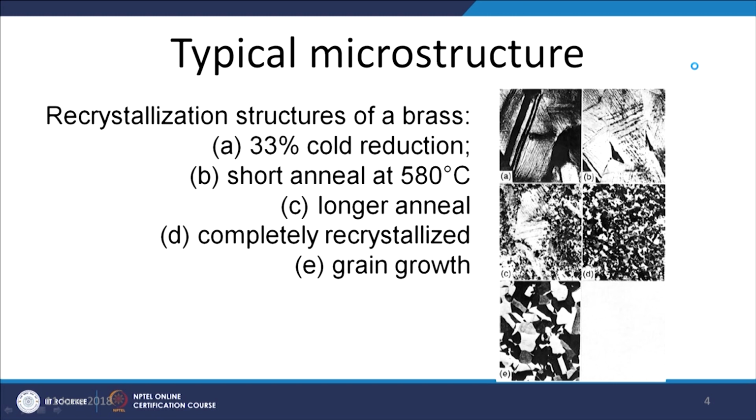Say, for an example, a metal which is subjected to plastic deformation by 30% cold reduction produces a lot of dislocations, which we can see from these very thin lines. All these are dislocations, and when we give exposure to a higher temperature for a very short period, some of these dislocations are annealed, or you can say annihilated, through the recovery mechanism. So, the number of such dislocations will be reduced.